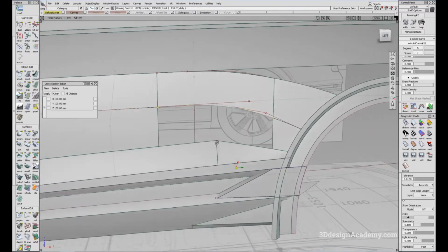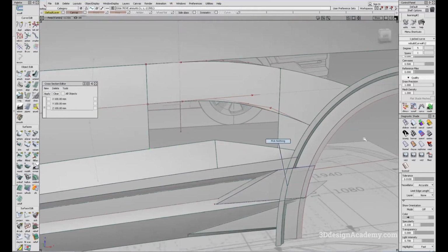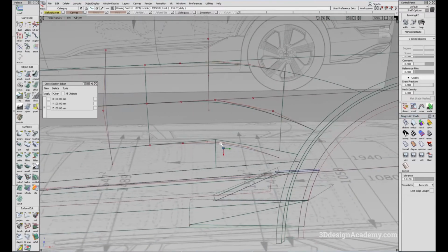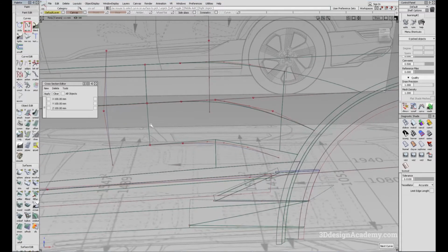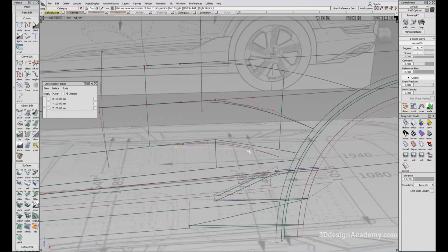Okay, so for this one, I'm going to copy paste this curve. And I'm going to say move pivot here, and bring it down here. The reason why I'm doing this instead of creating a new curve is because right now the proportions of the CVs are critical. If I were to just drag a CV from here to here and change it to degree 5, you'll notice that the spacing of the CV is a little bit different. And you want to make sure that the spacing of the CV is very harmonious between two curves so that it just works better.